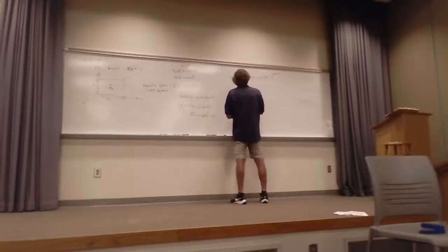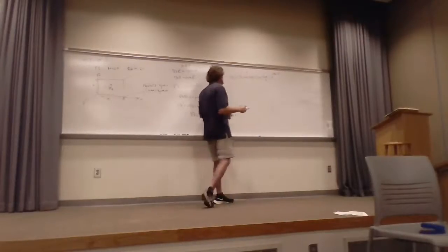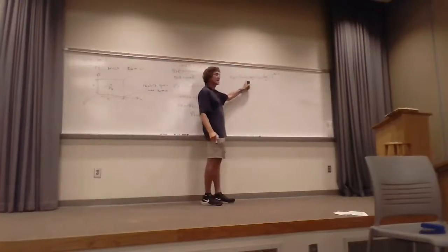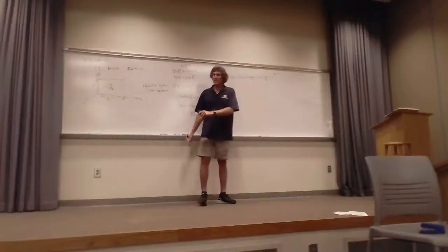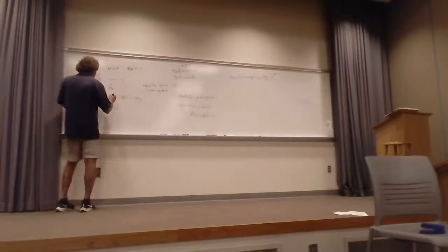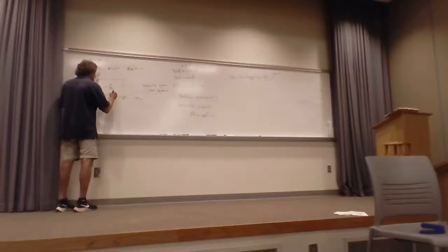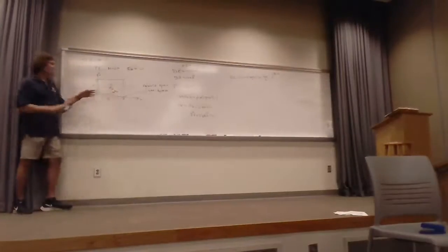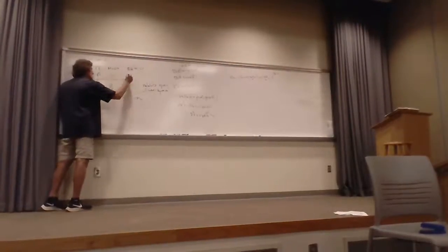Beta z is still the same in all these. Now, here's the reason it's cosine. It could have been a sine, right? But here's the deal. When you take a look at the tangent value of the magnetic field, this is something I hope you get a hold of. Remember, now we've got H in the Z direction, right? Well, Hz doesn't go to zero on a good conductor. That's a good conductor here and here.